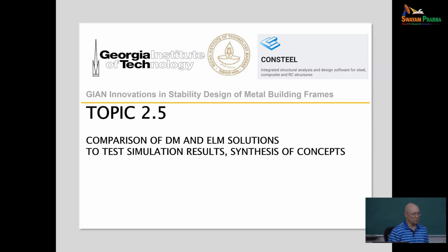So this is where my colleagues in Eurocode would say, look, we don't believe in stiffness reduction. We're just going to increase the notional lateral load. And so now you have to figure out how to get a notional lateral load that will work. But that's just Ayrton-Perry, essentially. We can figure out how to do that.